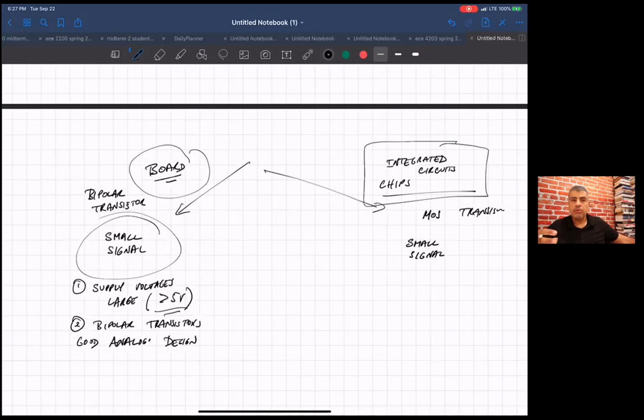And so all that really helps you to stay in the small signal model. If you're designing boards, you'd have to be doing something wrong not to be able to use the small signal model. It's maybe a good check on whether something bad's happened, like you peg some circuit or something.